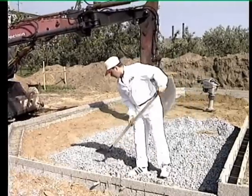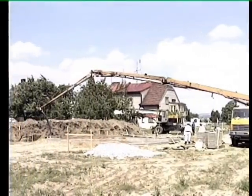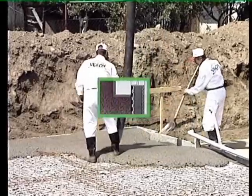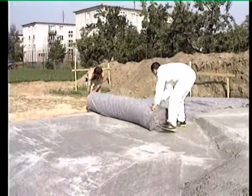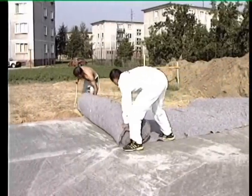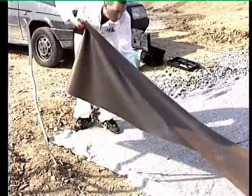After terrain modifications, the space between the foundation strips is filled with foundation concrete. The same procedure is used for buildings with cellars. After the concrete hardens, the foundation slab is prepared for the actual construction of the building. Insulating sheeting is laid and fixed to the foundation.